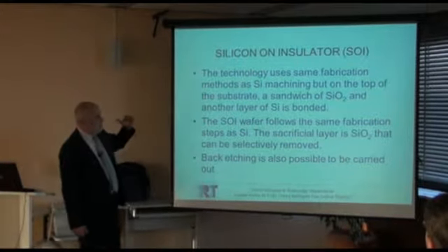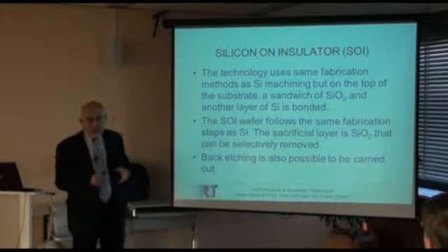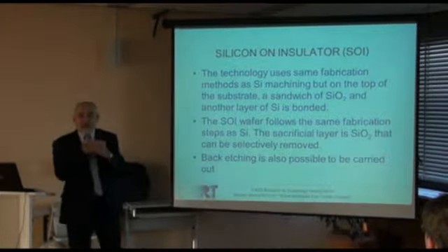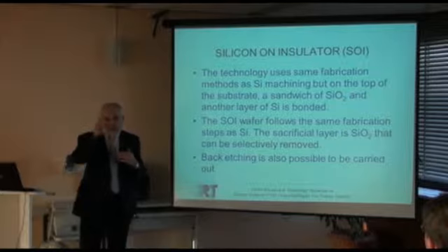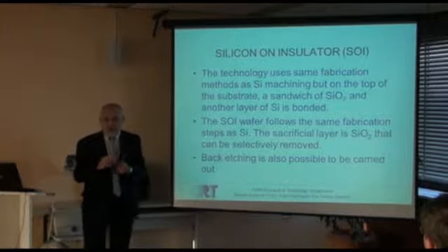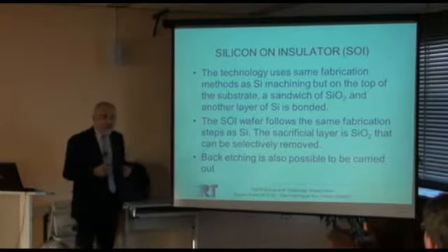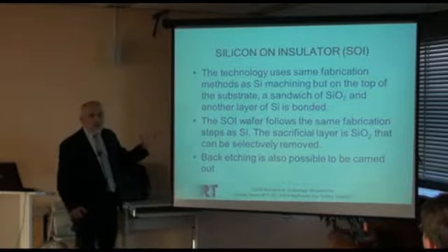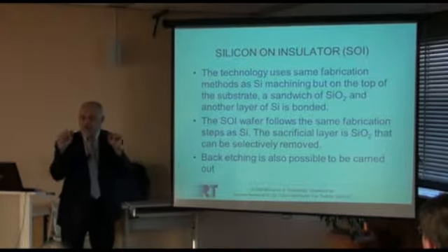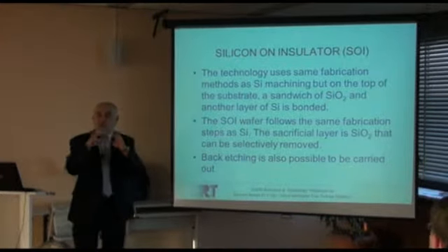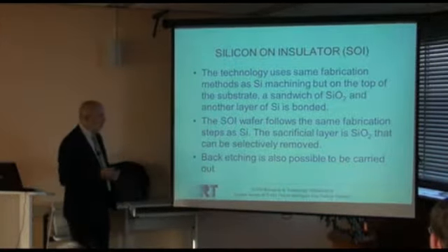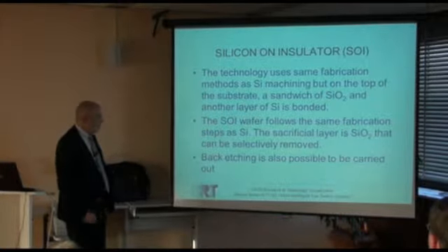Now, one could use this silicon on insulator, with silicon on the top. Either you can bond another thick silicon on the top, and have silicon, oxide, and two thick silicon layers with one oxide, and play with that, like a bulk. Or the work could go only on the electronics that will be built on the thin oxide and silicon on the top. Oxide and silicon will be the structural layers: membranes, measurement devices, beams, and so on and so forth.